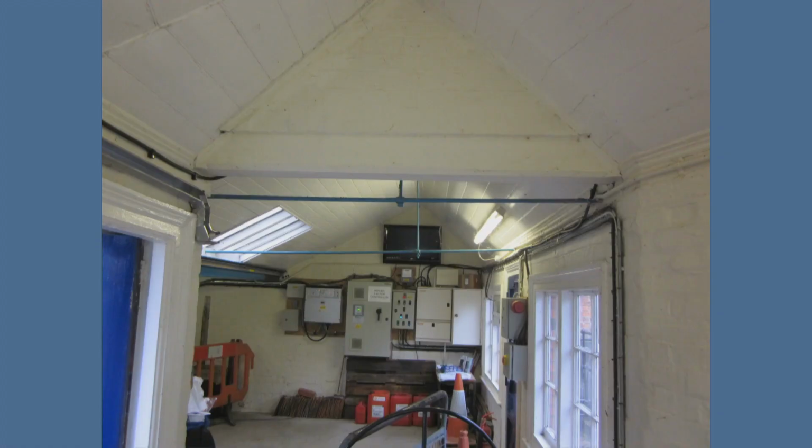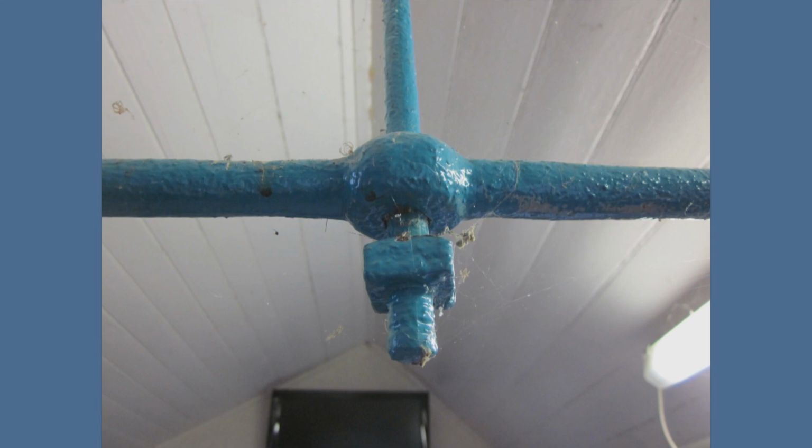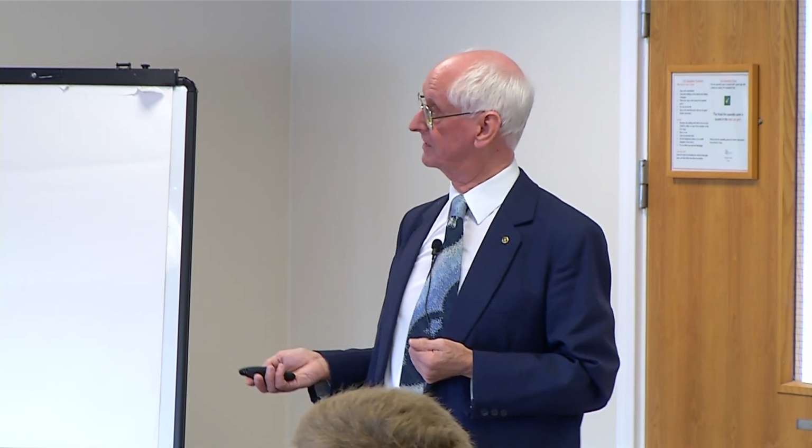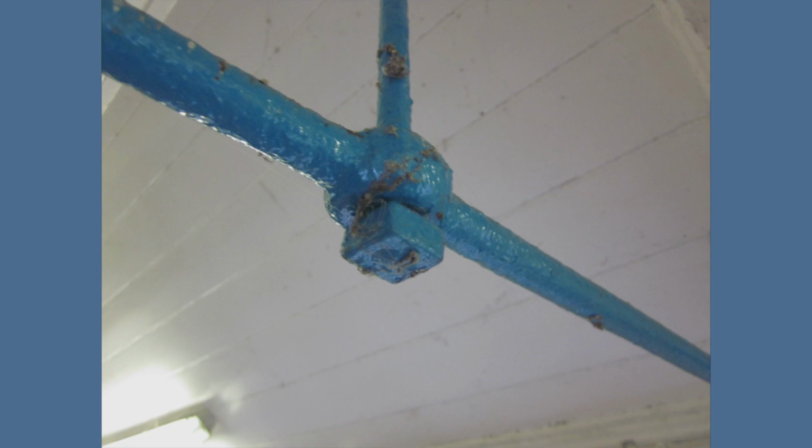And when we look at bolts, this is a nice little Victorian building, with a tie across and a hanger from the ridge. If you look just there, oh yeah, you can tell it's a handmade nut, and it's obviously not actually reached the point where it was supposed to be. This one is another one, same building, but that one's actually doing its job. But the handmade nuts are usually square. They find that these hexagonal nuts didn't come in until Whitworth started with his threads.